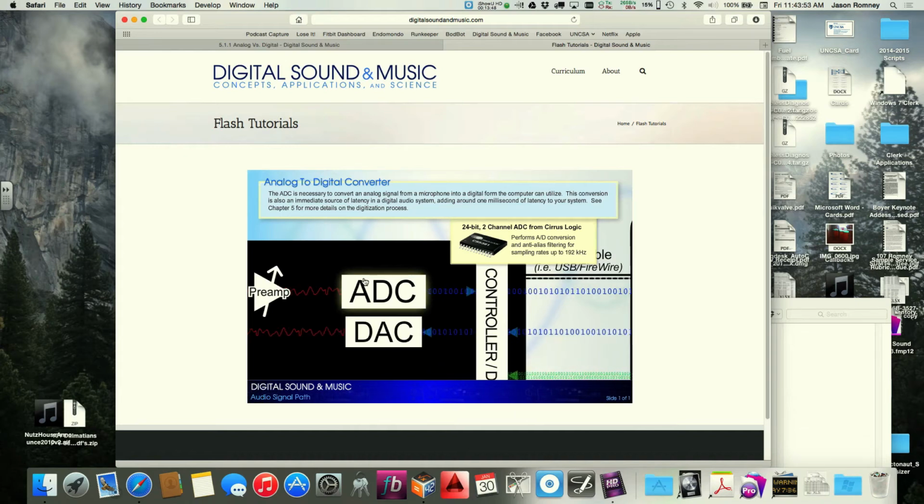But when you're in an environment where you might be recording, for example, latency can be problematic once it builds up. If you're tracking things and recording things one at a time, and you've got a musician listening back to what's been recorded and trying to play on top of that, if there's enough latency between when they do whatever they're doing and then when they hear it back on top of the track, that can be really tough for them to play on tempo and everything. And so you've got to be careful about that latency. There's lots of places you can pick up latency in the signal chain, as we'll see. But generally speaking, you're going to pick up a millisecond just in the analog to digital conversion.